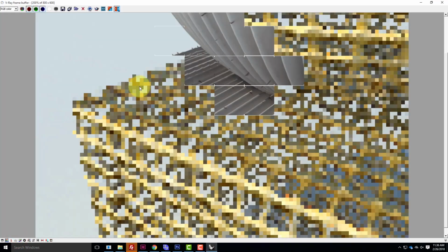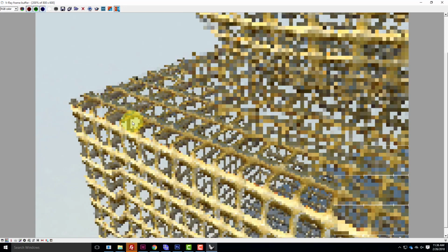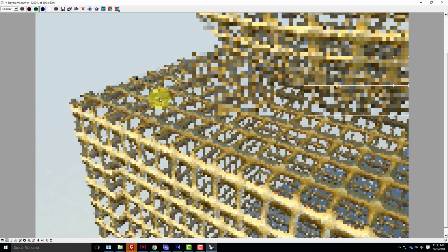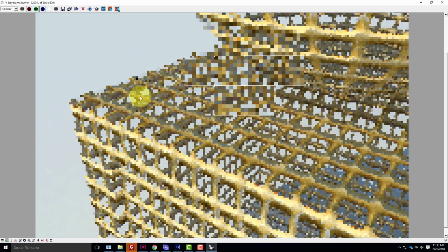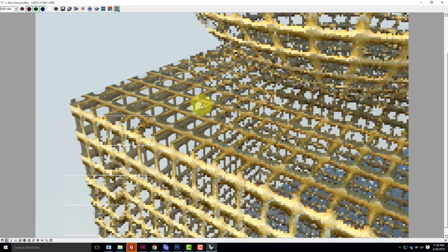we'll be able to see right through this as if it were a mesh. So we've controlled what parts of this surface are transparent. So we didn't have to cut any holes in the surface. So, frequently I see people, when they're starting to model, trying to cut holes through their surfaces. You don't have to. Just make a surface and then apply this on it. It's a much easier strategy. So there it is. We're seeing it as a mesh, and we're seeing through it.